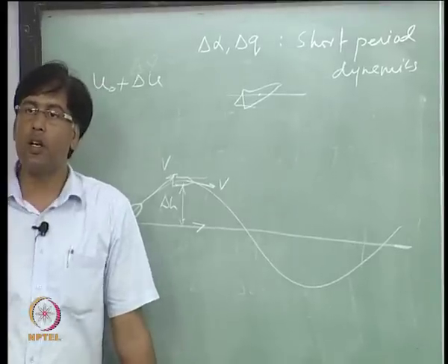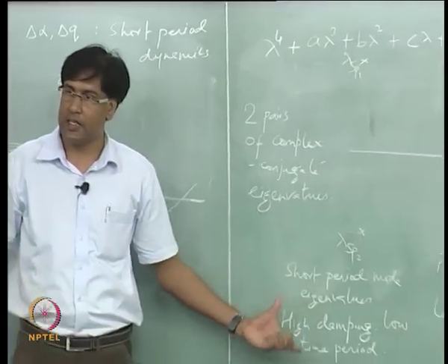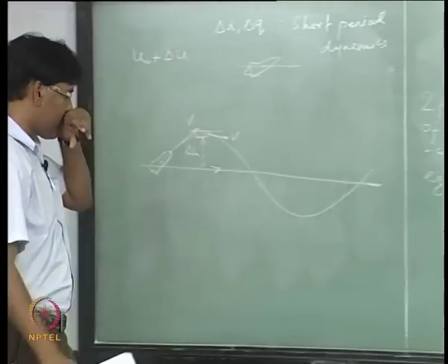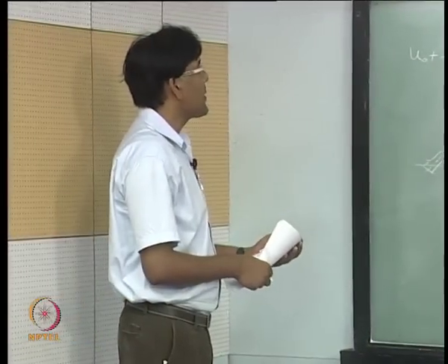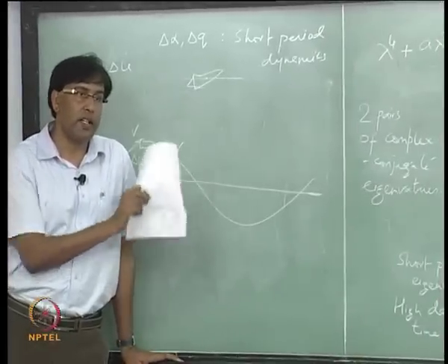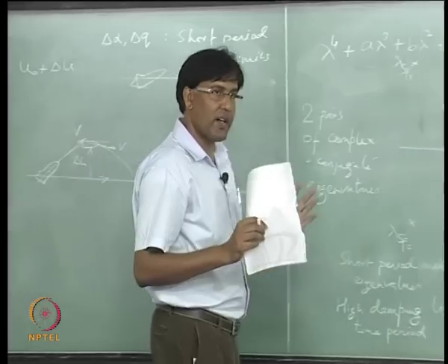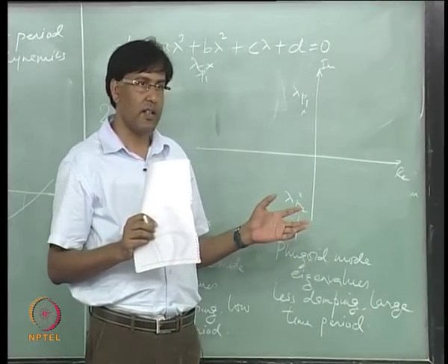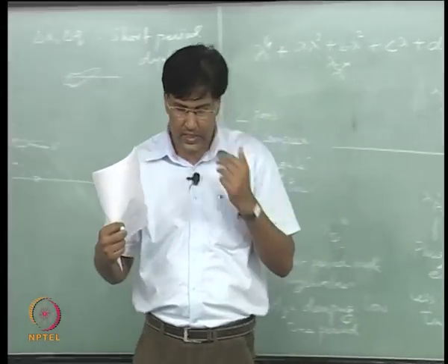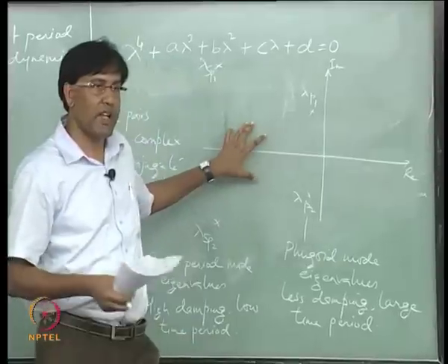that it actually damps out in very little time. That is what is short period dynamics. It's always true in this particular case, and we are talking about low alpha flights. In some cases it has been observed that they will come closer and merge with each other and then give rise to another type of dynamics.